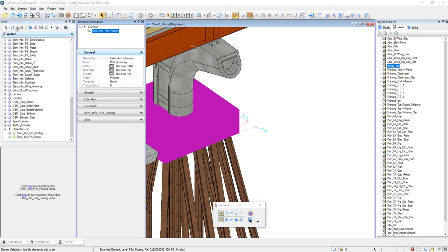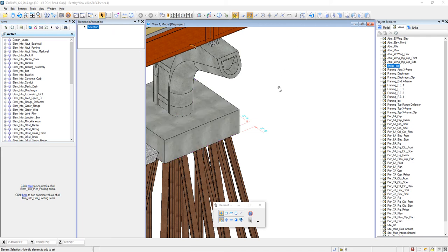One tool within the item browser is the search tool. Where that's going to be most useful, again, you can use it for anything, but I'm going to use it for searching for a bar mark, for example, because the bar marks are just labeled, they all kind of have the same alpha code. So there gets to be a lot of bar marks and they're difficult to group within the model. So let's first find a bar mark that we want to search for.